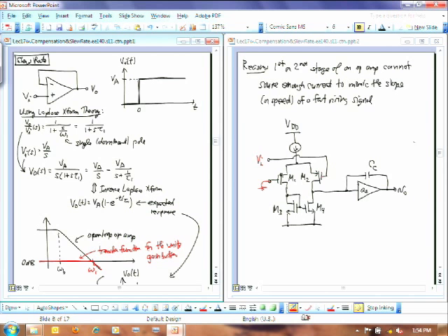And so when the current coming out of M2 is 0, all of this current, which I'm going to say is equal to 2 times I1, where I1 would normally be the current going through each of the transistors, now goes through this transistor, which is on. So 2I1 goes down that transistor. It keeps going down into this mirror, and it's mirrored out here, so I get a mirroring of 2I1 here.